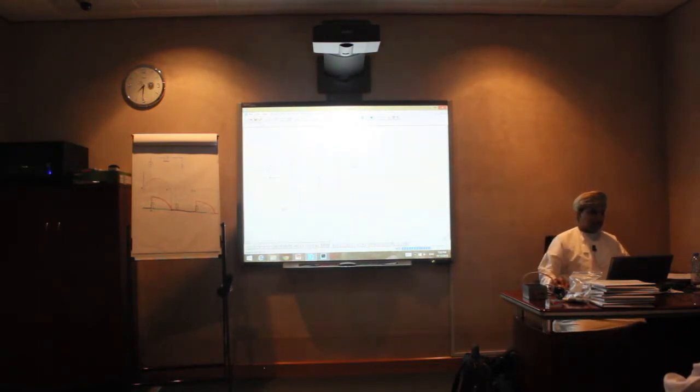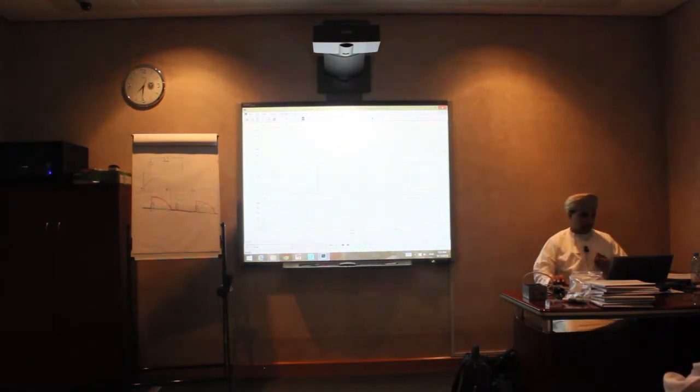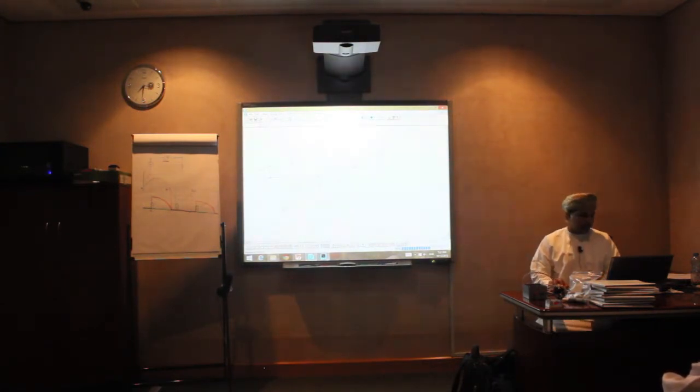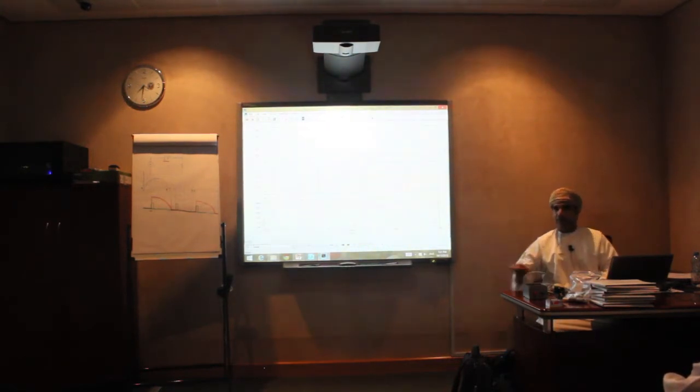And in the second half cycle, the same thing. In the second part, when I send this signal, the one in the arrow there, at that time the diodes D2 and D4 are forward biased. Therefore, they conduct, and we get this output voltage like that, and so on.